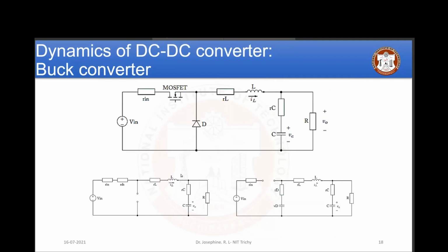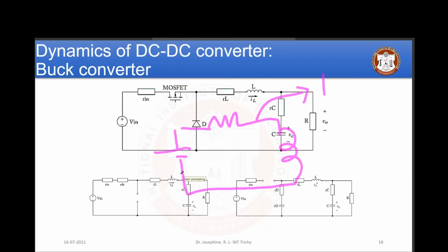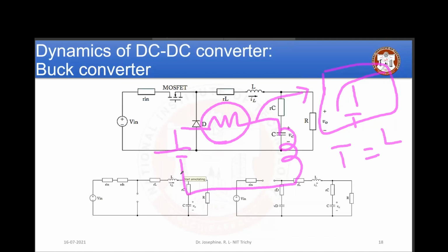There is something like this. You might have studied a simple DC source in series with a resistance and an inductor. If you give that ammeter reading to a DSO, it will show you that waveform, and you can find the time constant T, and you know this resistance. As you know, T is nothing but L by R, where R is nothing but R plus RSC actually.